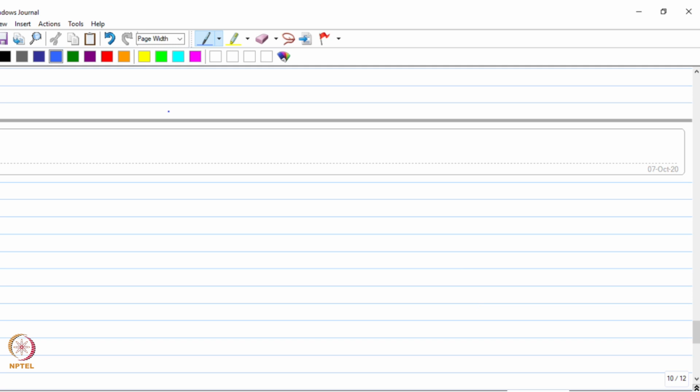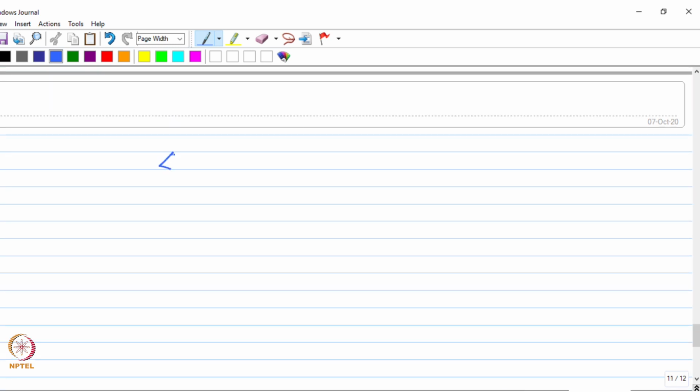Okay, so in the case of homogeneous nucleation, the critical free energy change is given by the surface energy and the volume free energy change. But in the case of heterogeneous nucleation, there will be an additional term in the form of the contact angle.